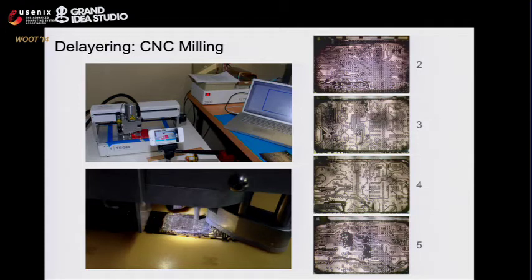But a trick with CNC and with most things that are very accurate is that PC boards are not planar. They're not completely planar as you would imagine. They look like it, but when you have something that has a 0.1 thousandths of an inch adjustment and is super planar, and then you put a board on there that, if you look at it under a microscope, is a little bit wavy, you're not going to always get nice clean access to each layer.